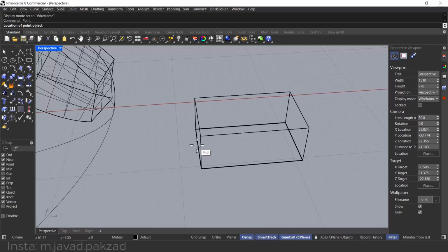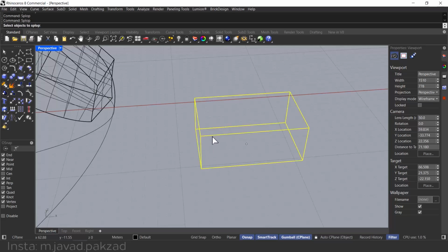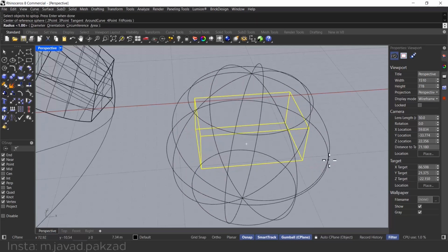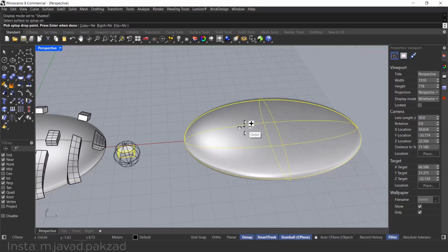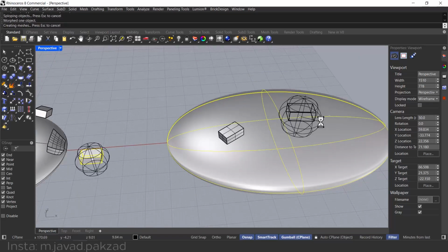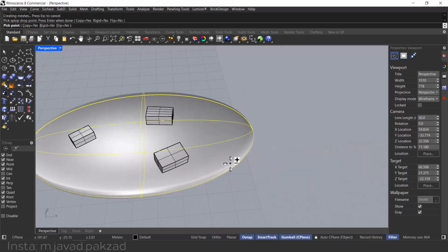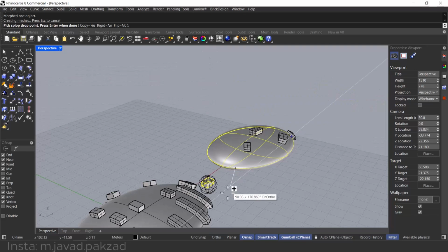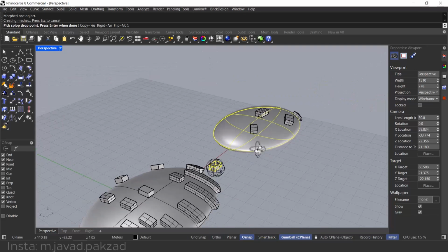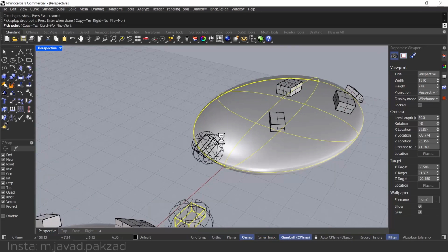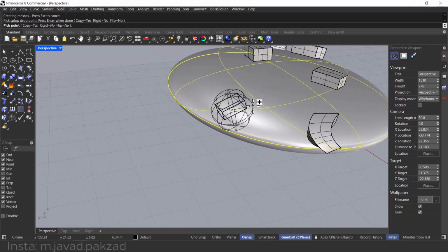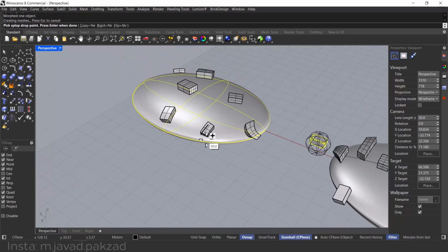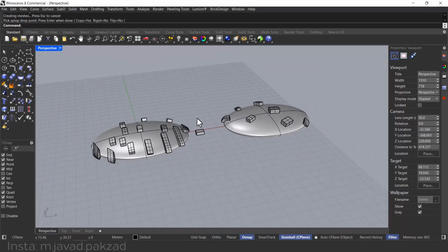Activate Smart Track. And now, I'm going to go ahead and use SP Loop. And I'm going to set this sphere around the object. And then after that, I can set the object on my surface. As you can see, we still have some deformities. However, it's not that severe. So this could actually be a good option if you want to set the objects on curved surfaces.